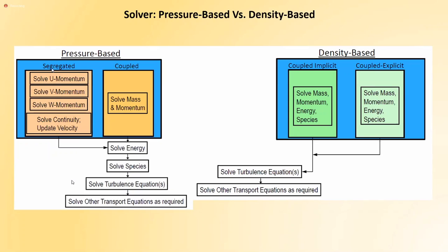Pressure-based solver could be used even till, I don't know, Mach 3, I think. You have the segregated solvers, which means the simple kind of solvers, and you have the coupled. Otherwise, it's quite the same.